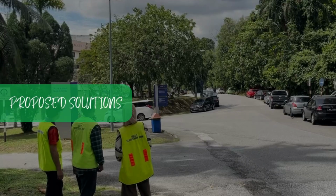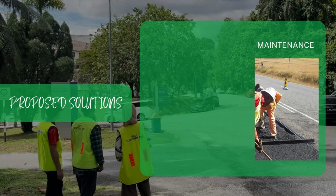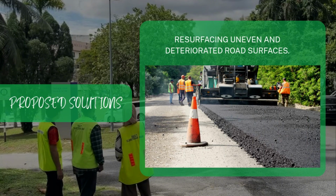To mitigate these problems, several solutions are recommended. The first solution is to conduct regular road maintenance such as crack sealing and patching to prevent minor defects from worsening. The second solution is resurfacing uneven and deteriorated road surfaces through milling and overlay, as recommended in JKR Arahan Teknik Jalan, to restore surface smoothness and proper road profile.